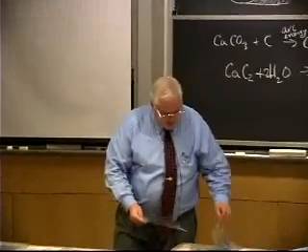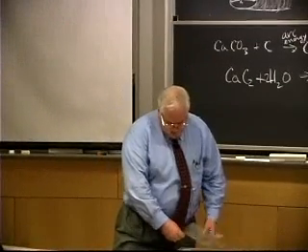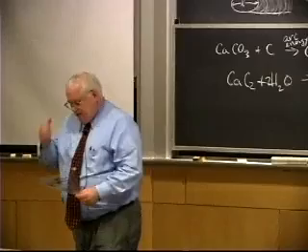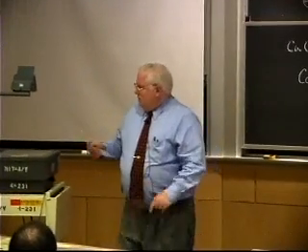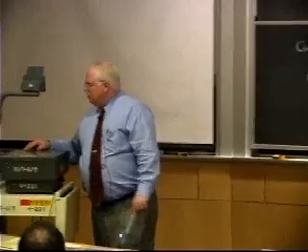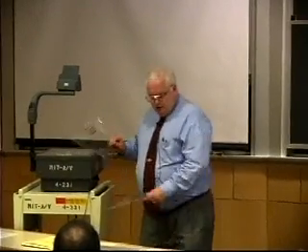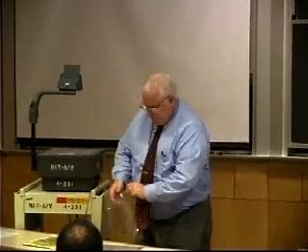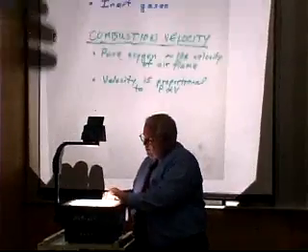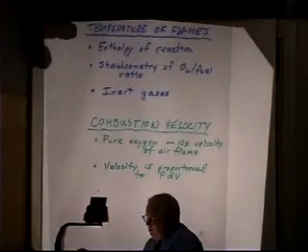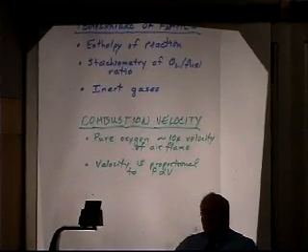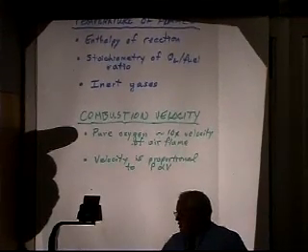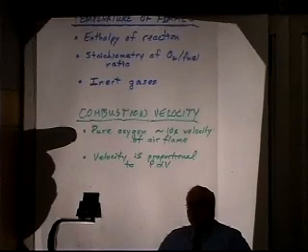So if we go back again to our flames, we can get different intensities with different enthalpies, different oxygen fuel ratios. It turns out, if I go back to this one, that inerts are important, stoichiometry and enthalpy. These are the 3 key things that determine the temperature. The combustion velocity: a pure oxygen flame with more PDV work will give you about 10 times the velocity of an air flame.